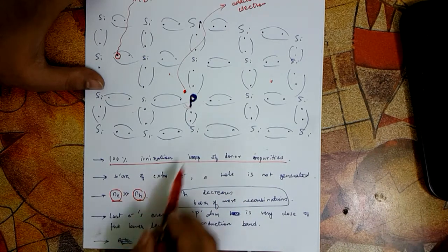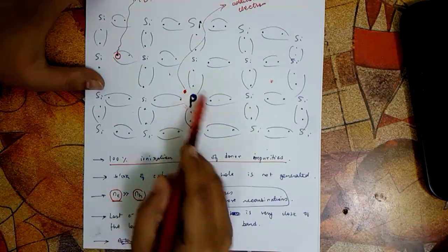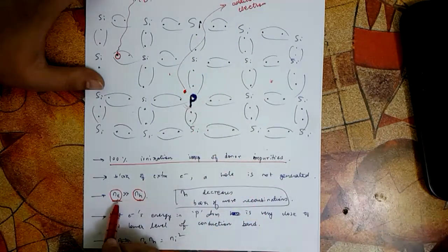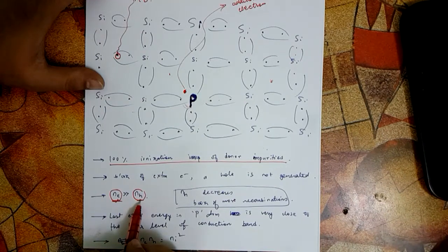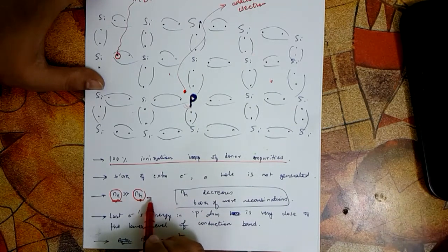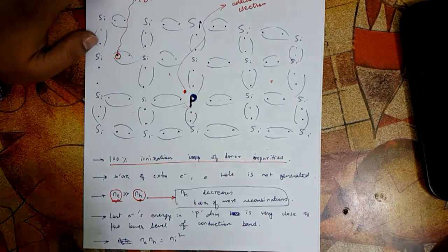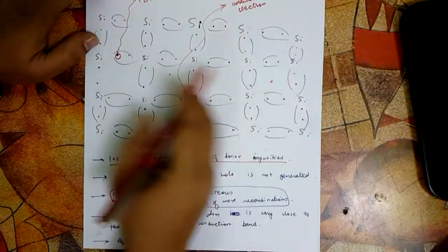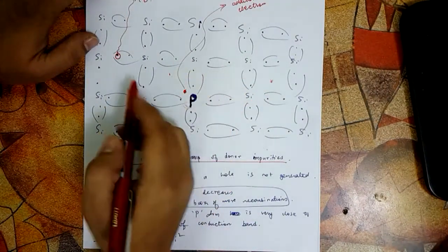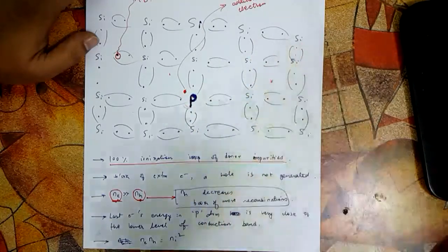and because of each electron going into the conduction band, no hole is generated, and the number of electrons becomes much larger, whereas the number of holes is not changed. But that's not the case actually. Actually, the number of holes decreases. Why does the number of holes decrease? Let's say in the silicon there were around 100 holes previously. And how many electrons were there before adding the impurity? Obviously, the number of holes is equal to the number of electrons.